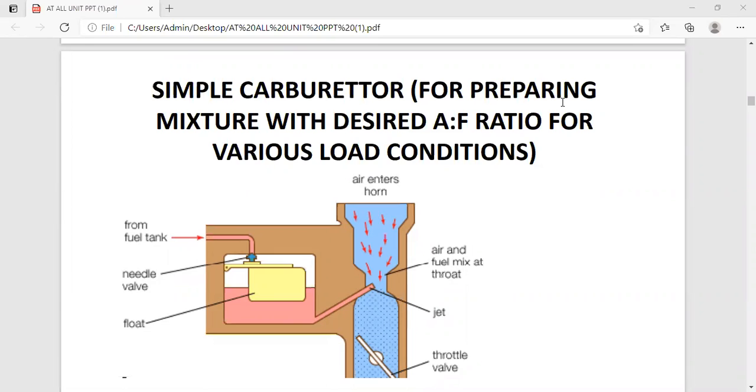If we are considering multiple cylinders, it has to supply the properly partly vaporized mixture to the engine. So it consists of supply of fuel from the fuel tank and air from the surroundings to the carburetor, in which the fuel is partly evaporated, and the partly evaporated fuel and air mixture from the carburetor is carried through pipes, and those pipelines are called the intake manifold.